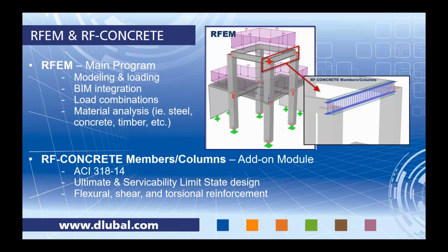Now, when we talk about add-on modules, today we will be in the add-on modules RF-CONCRETE Members and RF-CONCRETE Columns. This is what allows us to do design according to the ACI 318. Here we'll be doing ultimate and serviceability limit state design. We'll also be getting our flexural, shear, and torsional reinforcement from the standard as well.